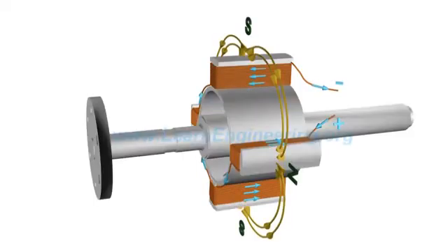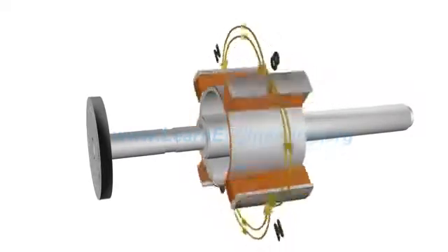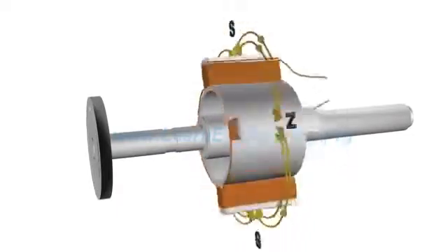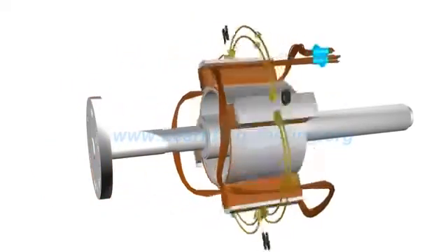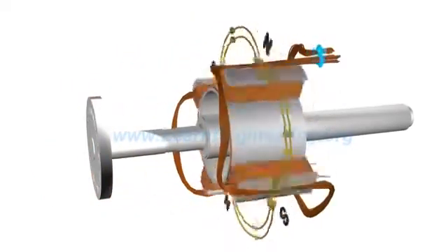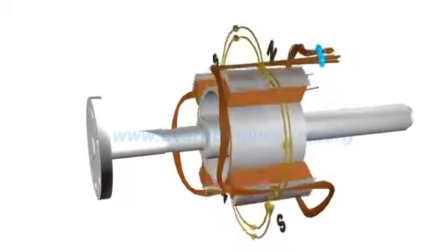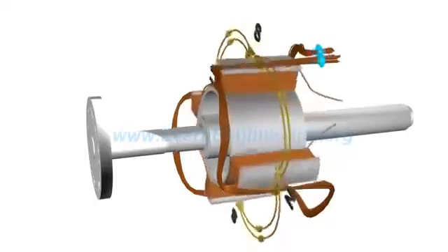The rotor is made to rotate by a prime mover. This makes the rotor flux also rotate along with it, at the same speed. Such revolving magnetic flux now intersects the armature coils, which are fitted around the rotor. This will generate an alternating EMF across the winding. Here is a slowed-down version of the rotor-stator interaction.